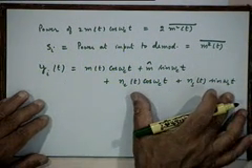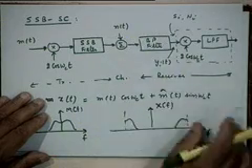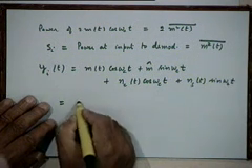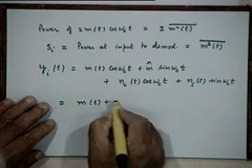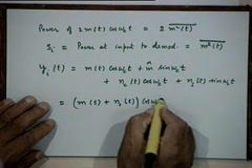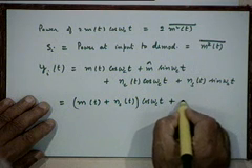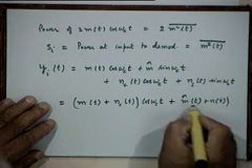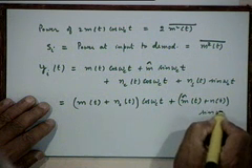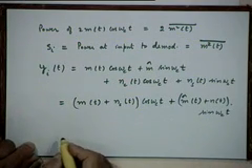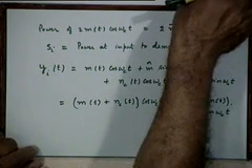This is a quadrature representation of the band pass noise that is coming out of the band pass filter at the receiver. So, this signal on the whole will have an in phase component which is mt plus n sub ct into cosine omega ct plus a quadrature part which is m hat t plus n sub st into sine omega ct, right. That is the input to the demodulator.